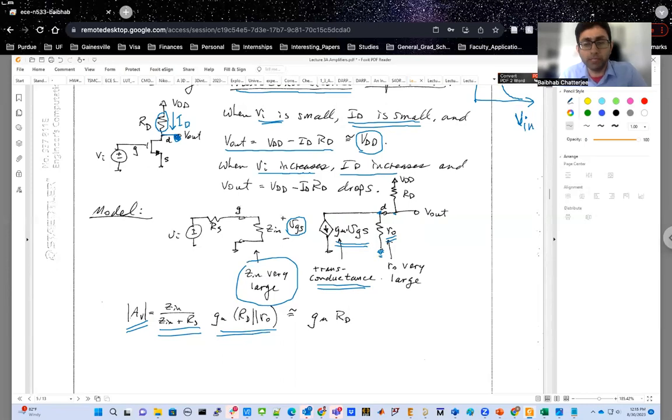Now, in terms of AC, in terms of alternating voltages or currents, a ground is a zero potential. Similarly, the VDD, even though it's a supply of your circuit, in terms of AC, it is a zero potential because there is no fluctuation in the VDD in an ideal scenario. What is an ideal VDD? Let's say you have a 3.3 volt VDD or a 5 volt VDD and a 0 volt ground. There is no fluctuation in the 0 volt ground.